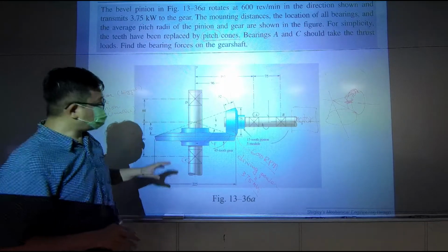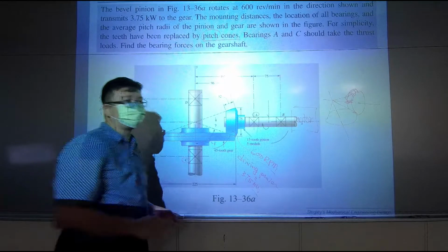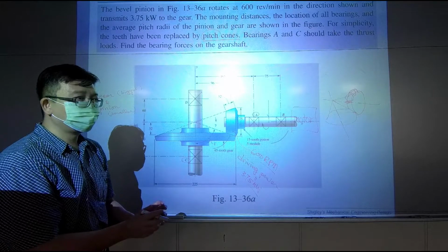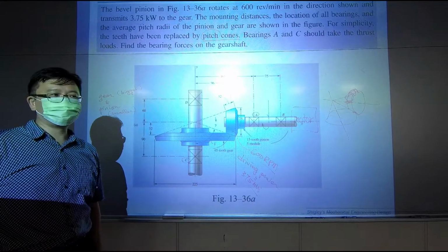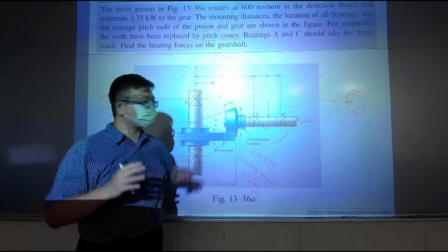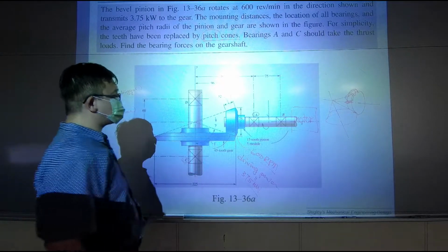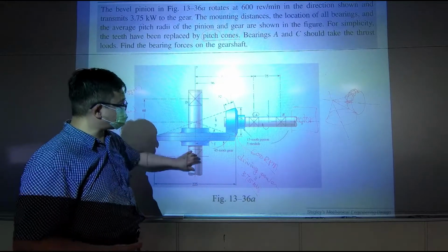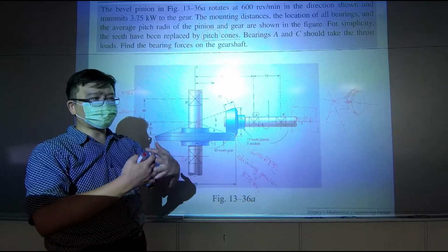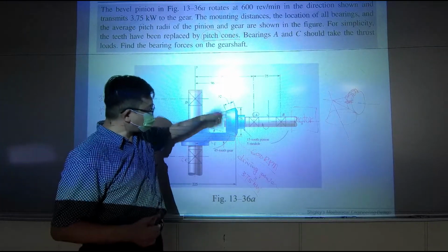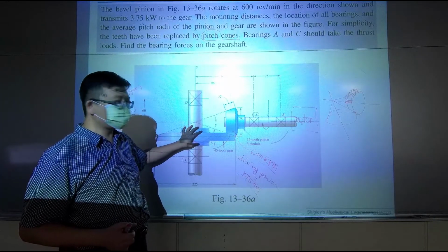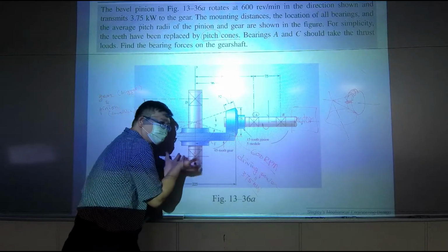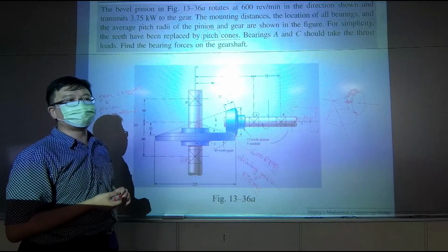If on each side there's nothing holding the mechanical component, it will fly away immediately. Imagine these two shaft systems connected like this, and nothing is holding the shaft or the gear. When you turn on the motor, the driving force is so large this gear will be pushed away. So something must be holding that strong force.